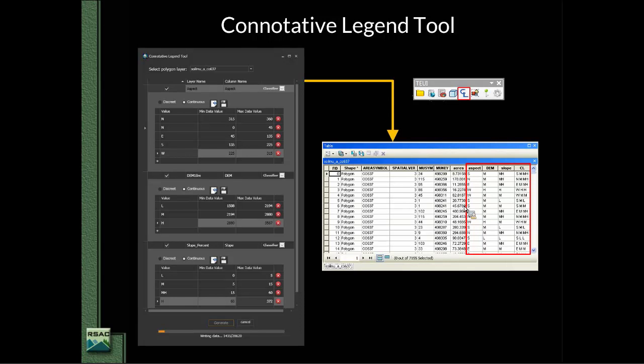Or if you want to do this in an iterative process, you don't have to keep typing in the classification schemes. Essentially, the tool goes in and looks at under each zone or under every polygon the majority value and assigns the polygon the letter or the number that you selected for that class, and then concatenates them all together into a single symbol at the end.